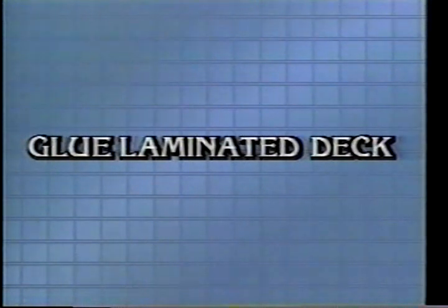The glue laminated decks, where you had 4-foot wide panels, reduced that cracking, and the only places we normally would see cracks then are between the joints of the planks. We have gone further with that and have used dowels, which sometimes helps reduce that propagation of the crack between the glue laminates.